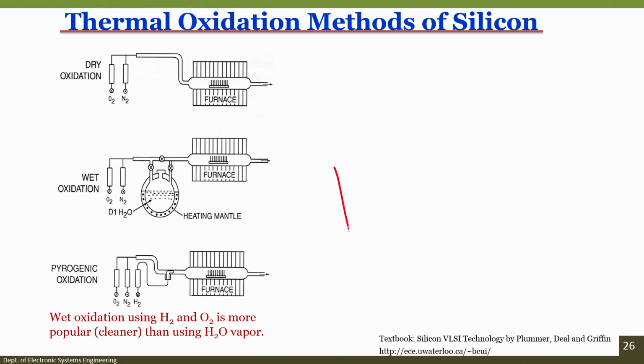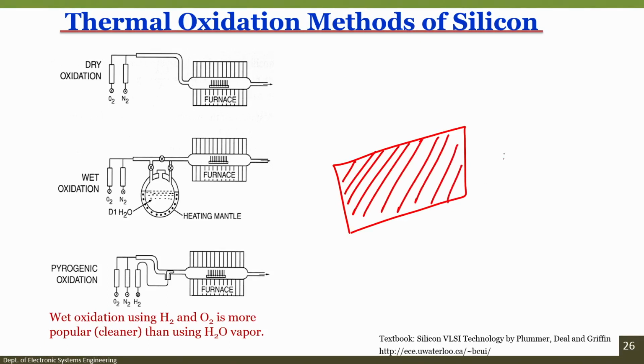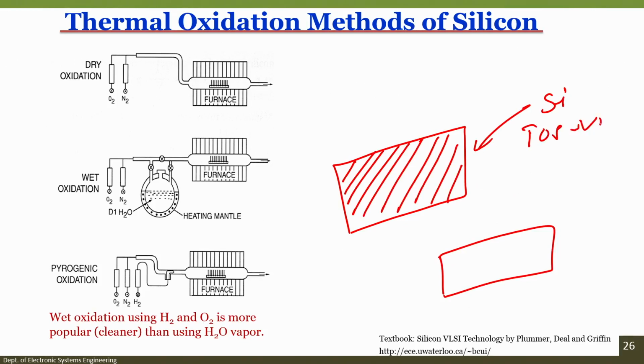The reason is that we will form a chip that is coated with a metallic layer, and the base can be silicon. But if I deposit, this is the top view, and this is a cross sectional view, if I deposit metal on silicon, then it is a short, right, because silicon is a semiconductor.